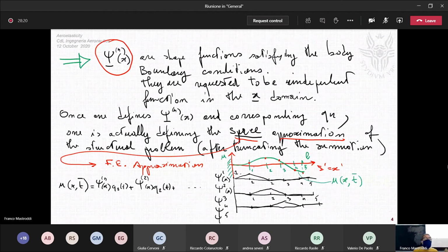But if you used different connection lines between the 1 value and 0 value, you would obtain another trend for connecting the point on node 1 with the point in red on node 2 and so on. But in this case, the approximated function is this here. After this summation, you should have the red line like this, this, this, this. And ladies and gentlemen, this is the finite element approximation of our analytic function.